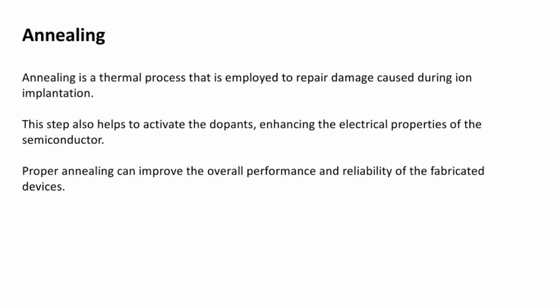Annealing. Annealing is a thermal process employed to repair the damage caused during ion implantation. This step also helps activate dopants, enhancing the electrical properties of a semiconductor. Proper annealing can improve the overall performance and reliability of the fabricated devices.